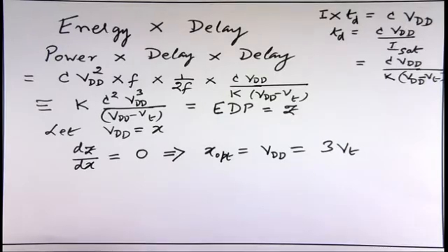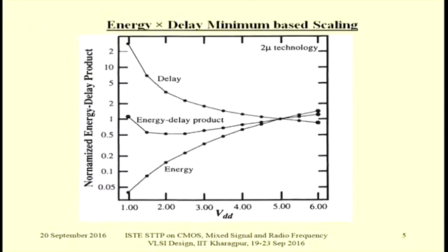So that means this energy delay product can be minimized somewhere here. Now, how much can you vary the power supply voltage? We have to make a trade-off here: the delay should not be allowed to go up very much so that the throughput suffers, and at the same time the energy should not be spent much, so that we do not suffer from some runaway problem and consequent heating. So we have to make a compromise between the increased delay and the reduced energy. We have to maintain throughput.